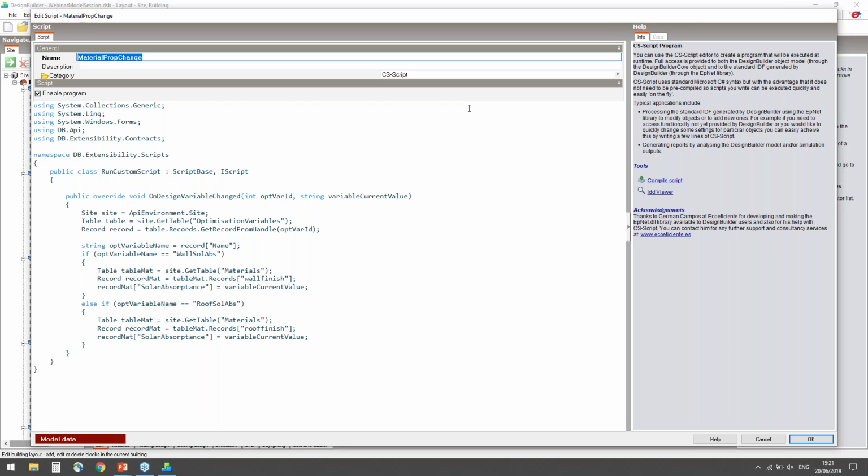Scripts like this one unlock the DesignBuilder's API for modification and can be used to set any available API environment property. They use hook points typically before and after simulation to either modify the default IDF generation by DesignBuilder or to access DesignBuilder model inputs to modify or control them. Also, they can access output data to produce custom reports. It is better to explain parts of this script on the slides so that I can easily highlight the part as I discuss.